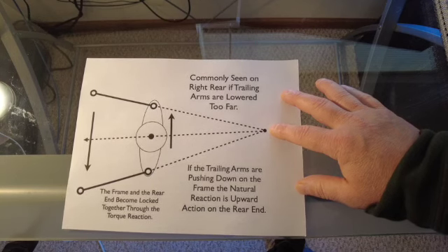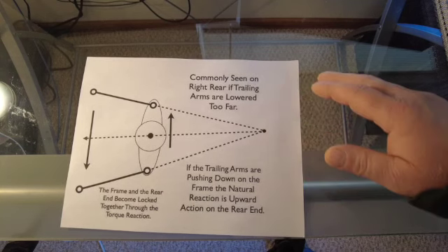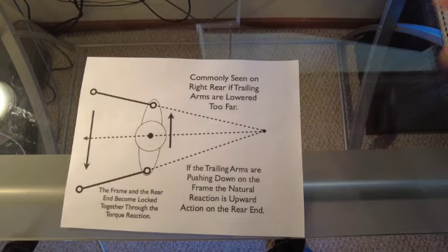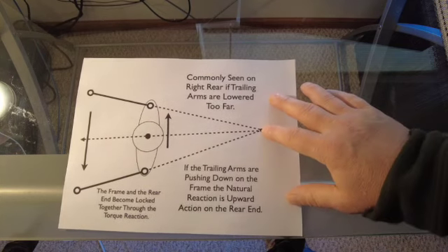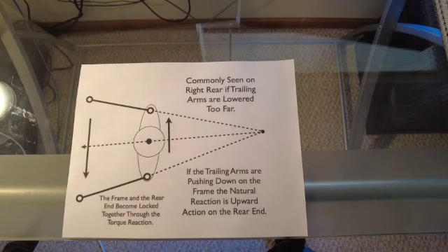But if you're ever at the races and you have your smash machine in the race trailer and you want to change complete packages to put on your car with different springs and everything, or even you might want to adjust the smash number a little just for some wedge, it is ultimately important that you have your own numbers and you change your spring and you return to that smash number with that different spring.